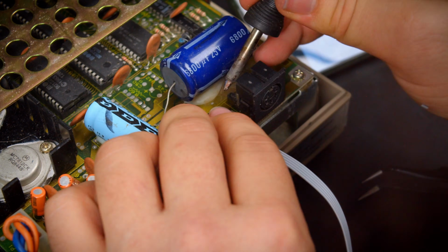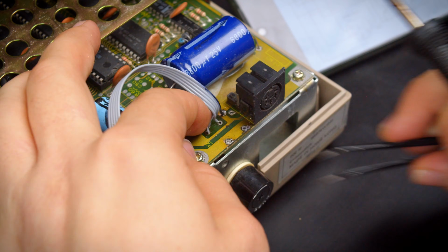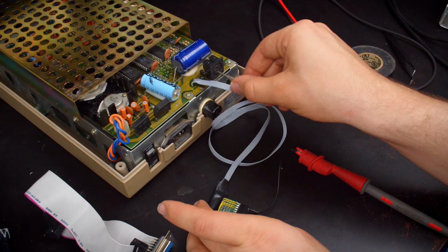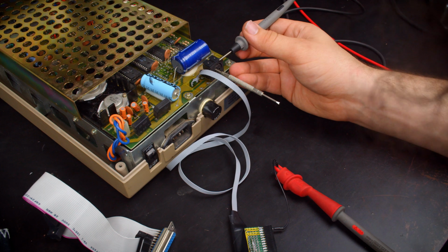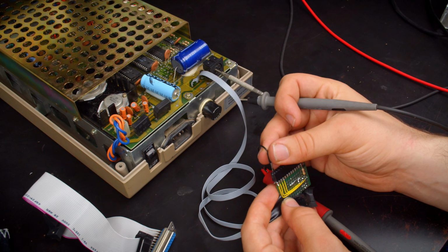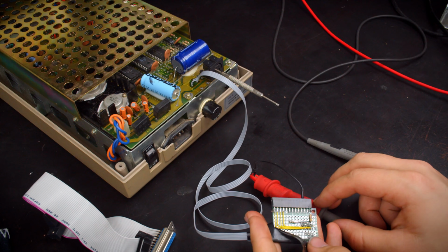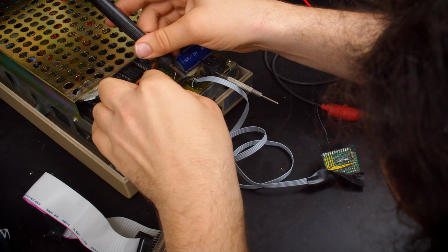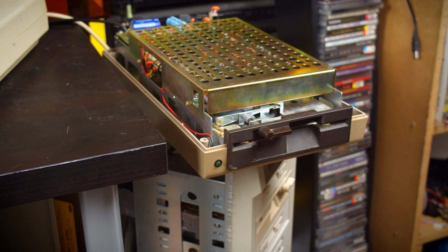Once the board was done, I soldered it to the missing DIN connector on my 1541 drive. Then, as a precautionary step, I checked all my work to ensure everything was connected where it needed to be, which was a good thing because I actually got 2 of the wires wrong on the DIN connector. Now that everything is good to go and it looks like it should work, I put the drive on top of my 486 and it didn't work.